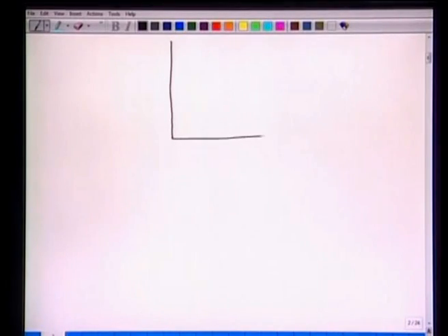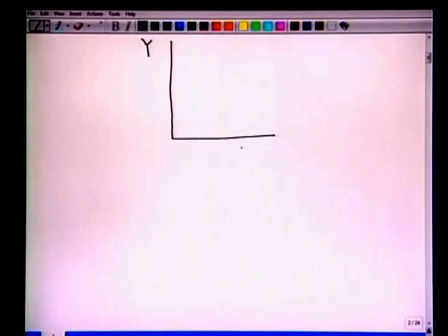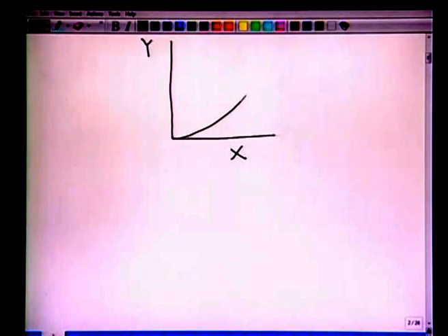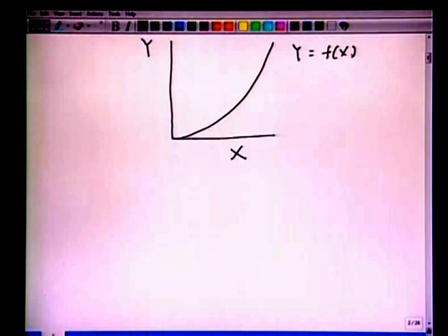Alright, but we must also understand that whatever we can do graphically we can also solve mathematically by writing down these equations. So let us redraw this curve of operating lines and equilibrium curve. We have y versus x. Let us assume we have the equilibrium curve like this, and we have been given this equation y equal to f(x). We know these points, we have x2 and we have y2. This is at the exit end, and we know y1, the feed concentration in the gaseous phase,